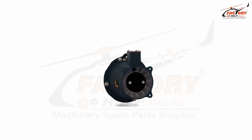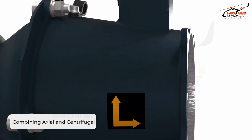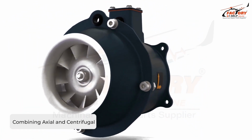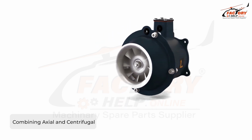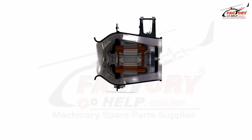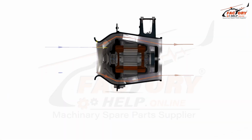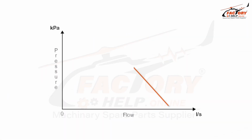That brings us to the mixed flow fan, and as its name suggests, this type of fan combines elements of an axial fan and a centrifugal fan. So how does that work? The fan uses an efficient airfoil blade, like an axial fan, but wider and arranged around a conical hub. Combining these features generates a flow typical of an airfoil blade, but forcing the air to flow past the cone introduces an axial and radial characteristic to the airflow.